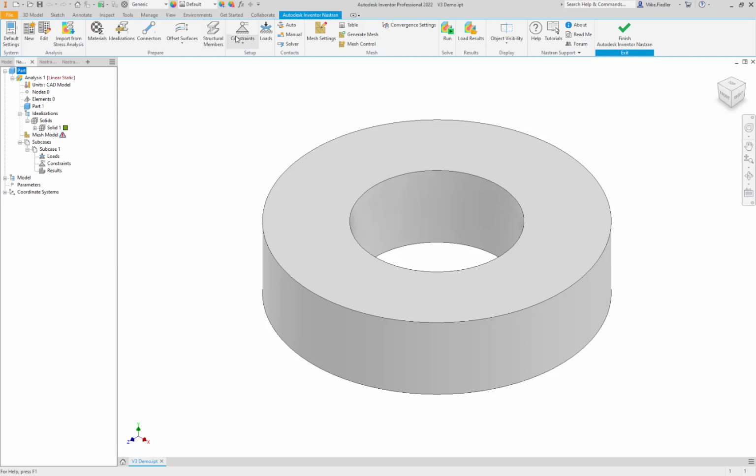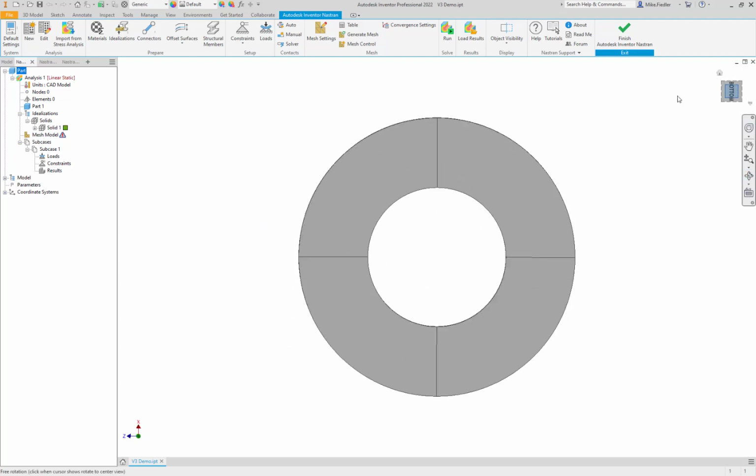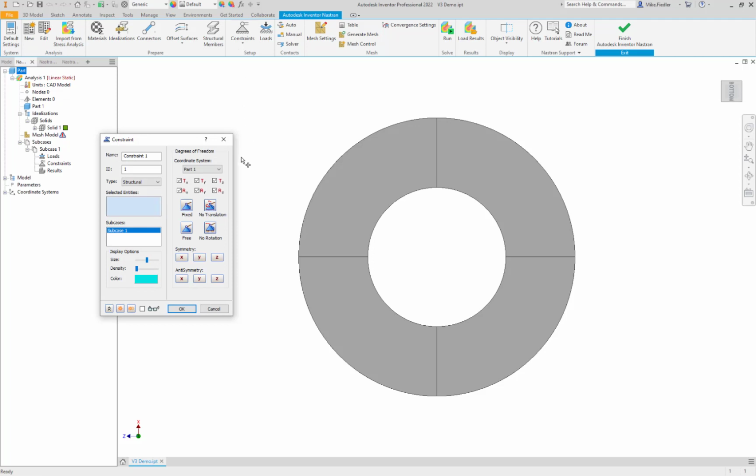And I guess next we can add in our constraints. So let's take a look at the bottom of this model. And we're going to go into constraints. And basically what we're going to do is add radial internal pressure. So it's going to push the geometry outward. You can envision that any nodes along the line here between 12 and 6, as my mini axis is oriented, should move purely in the x direction due to that pressure, so they shouldn't experience any z direction movement.